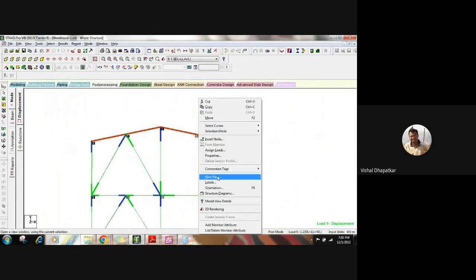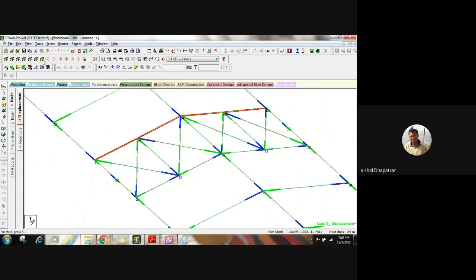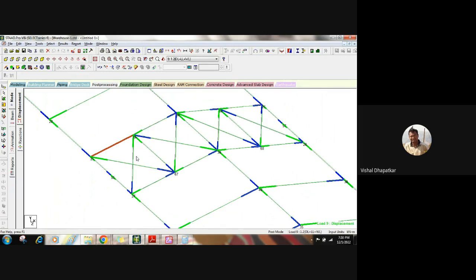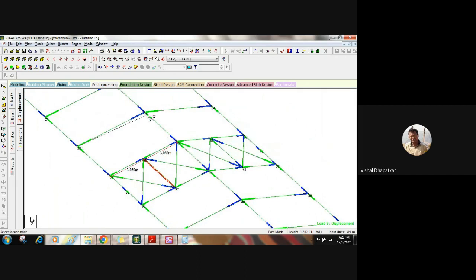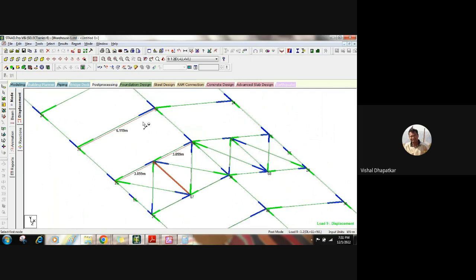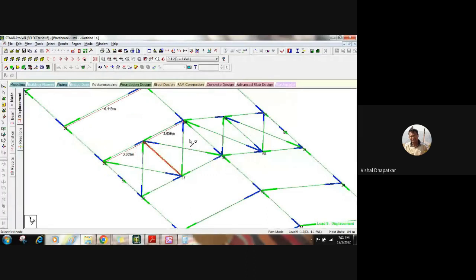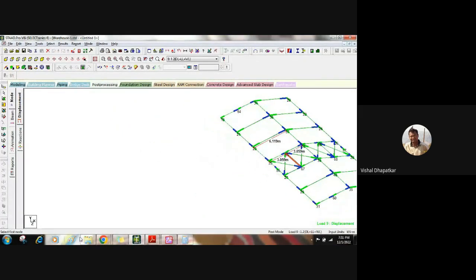So in this case, for this beam, I think we have discussed in one of the sessions also while assigning the parameter. So if this is the beam, since I have bracing here and tie member here, then my Ly will be 3.059. For this member also 3.059, right? But Ly for this member will be 6.119, right? Lx for this member will be, it is completely lateral torsional unsupported member. So the length for this member is 6.119 Lx, but for this member it will be 3.059, 3.059. Okay, so I'll just prepare some sketches. Have you understood this Lx, Ly, and Lz parameters?